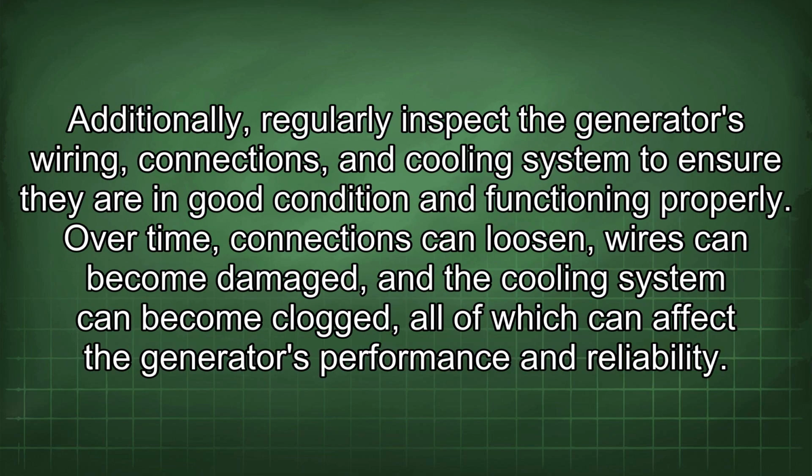Additionally, regularly inspect the generator's wiring, connections, and cooling system to ensure they are in good condition and functioning properly. Over time, connections can loosen, wires can become damaged, and the cooling system can become clogged, all of which can affect the generator's performance and reliability.